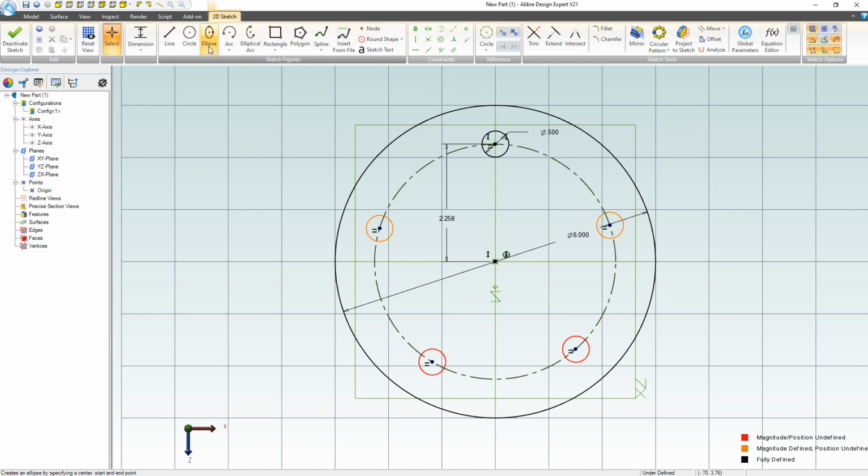Okay, I want to do this fully constrained, so we'll just grab a construction line. And I can simply give that an angle, right, of 360 divided by 5 is what I meant to say. There we go. Let's try that again. And I think it'd be convenient. Let's draw line, line, and yet, you know what? I don't think I need another line there. Let's just do another 72-degree angle.